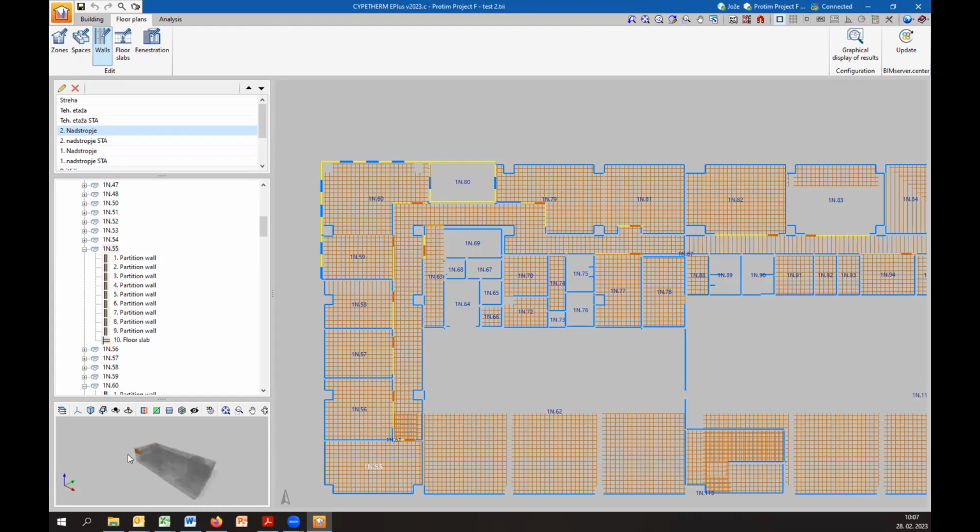Yeah, this is not right. This is not defined correctly. So again, two options. My recommendation is, okay, let's go to Revit. We have identified the different problems. Let's go to Revit and let's adapt the Revit model before exporting to solve the different issues we have found in our way. Yeah. In this case, I will recalculate all the volumes of the different spaces, disabling the layer of structural columns.